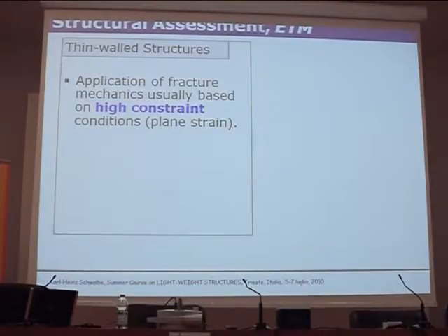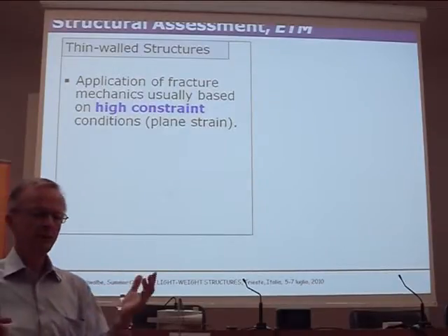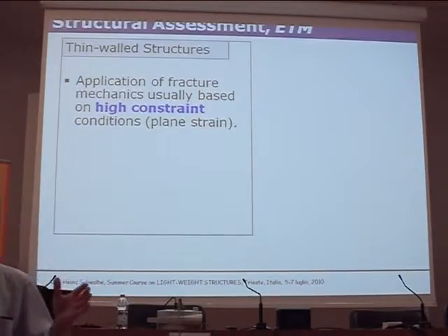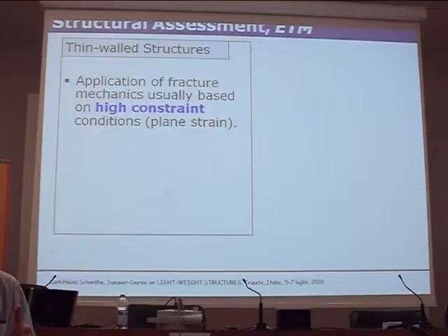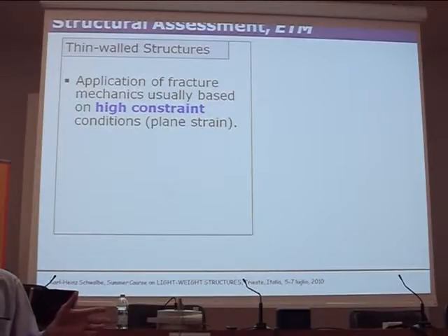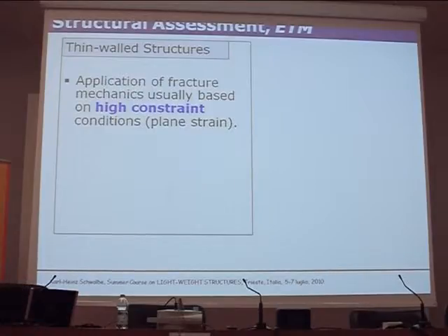The stress triaxiality depends, among other parameters, on the thickness. Had I a relatively soft or low strength steel, S355 or whatever, 300 millimeter thickness is just sufficient for plane strain. We machined such a specimen, a CT specimen, 300 millimeters thick. We had a test machine which we could use to fracture the specimen. We never did it. The specimen was so expensive that we used it as something to show our visitors.